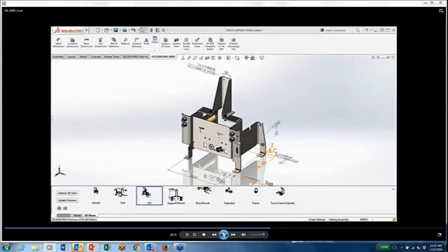So if your process is used to sending parts along, where you send the part to manufacturing and you also send a critical dimension drawing before the actual drawing is done, you guys are right in line with what MBD is all about. Instead of putting the dimensions in a critical dimension drawing, put the dimensions directly on the 3D model. All right, that's SOLIDWORKS MBD.